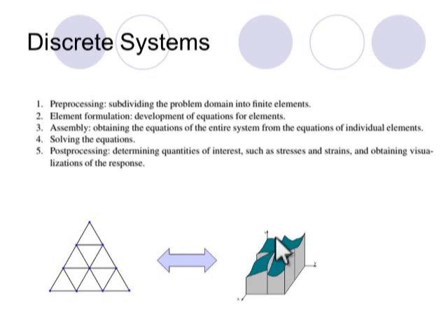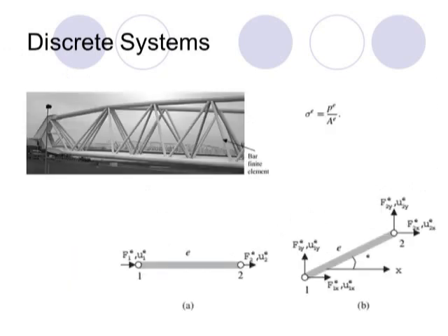And by using the combination of these functions, we find how the displacement varies. Of course, we know that the strain is the derivative of the displacement, roughly speaking. Then we take the derivative of it and we calculate the strain, and from there we calculate the stresses. This is what we do in a discrete system. So basically, the first step is to obtain the discrete system of our engineering problem.